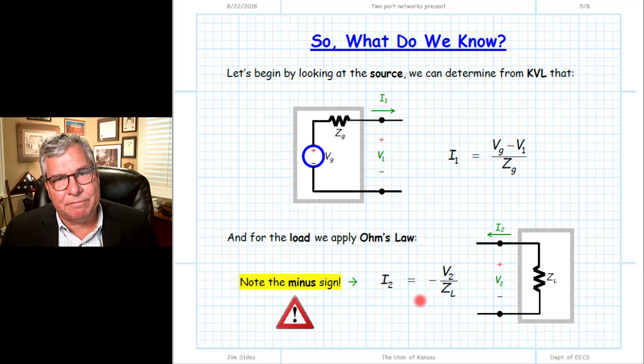So this is a frequent error that students make when they try to use transimpedance parameters to solve circuits. They write equations that are not consistent with the notation. And again, we have to go through and use our current and voltage notation this way. Positive current is always defined as flowing into the multiport device for which we have our transimpedance parameters.